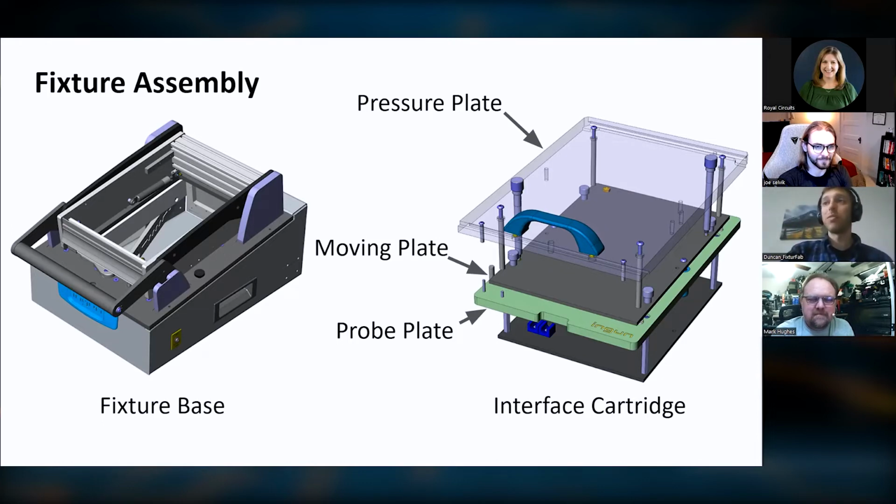Those quick little fixtures are great for development, especially when you're first working on a project or bringing up a circuit board. We used them a lot at a company I used to work at, where all the circuit boards were really small and there wasn't space to put a programming header or a Tag-Connect set of pads. To do the programming and firmware development, we would make these little development fixtures, as we'd call them, put the little board in, and slap it in. Then as you're doing the firmware development, you can just program it straight from your computer in the fixture, instead of having to bodge wires all over the place to connect to the programming pins.